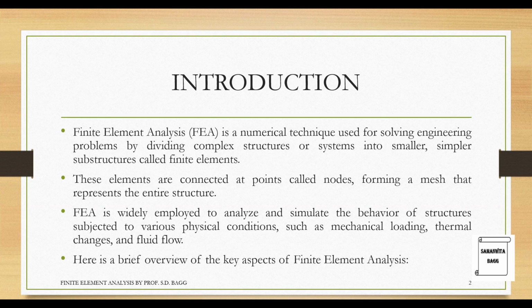Finite element analysis is a numerical technique used for solving engineering problems by dividing complex structures or systems into smaller, simpler substructures called finite elements. These elements are connected at points called nodes, forming a mesh that represents the entire structure. FEA is widely employed to analyze and simulate the behavior of structures subjected to various physical conditions such as mechanical loading, thermal changes, and fluid flow.